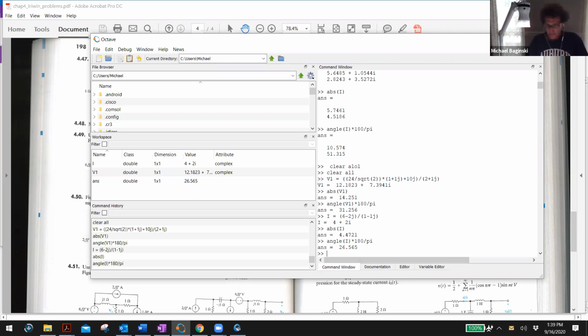Another question. I'm trying to just flesh out anything with complex numbers. Ultimately, let me make one comment. What you really do, since this is steady state, this is something at a continuous frequency. I mean, the frequency never changes. It's like the voltage out of the wall. What you're doing is, instead of using a, quote, resistance that's always a real number, you're replacing that resistance with a complex number, possibly. Now, instead of having just 10 or 100 or 1,000 ohms, you could have minus J10 or plus J10 or 10 minus J10. You follow me? That's the only difference.